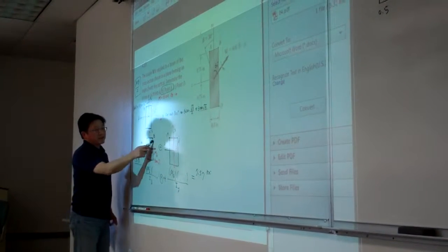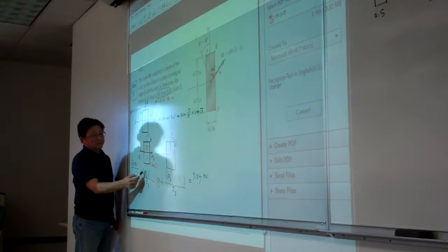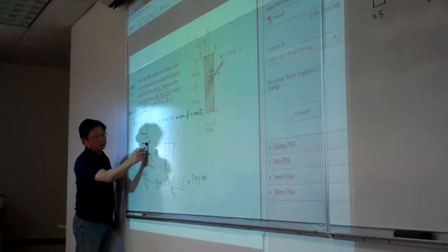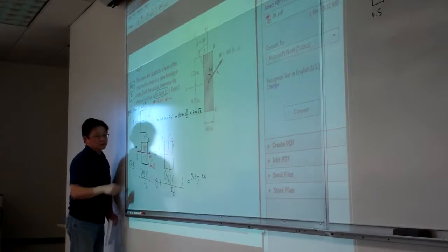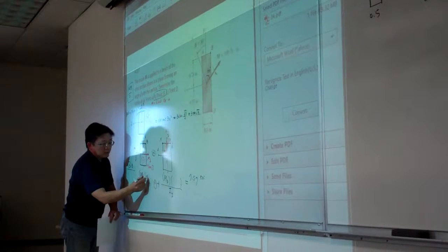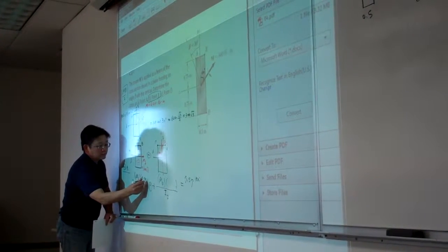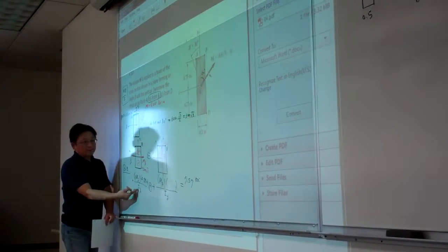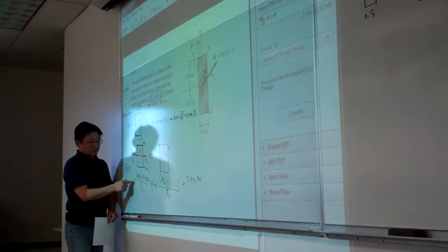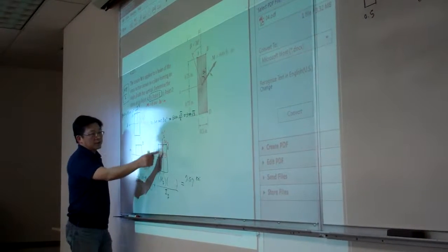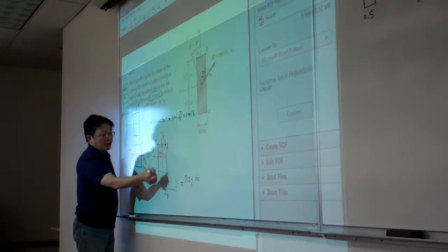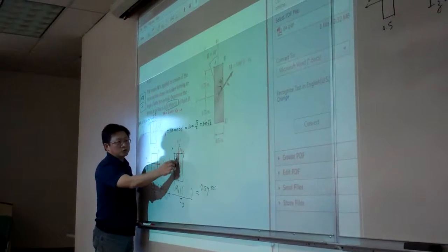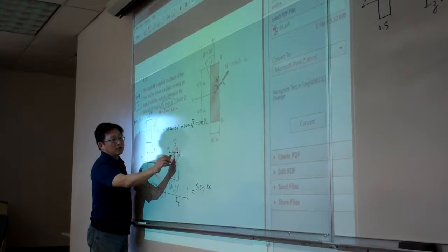Okay, now for this case, and again, the bending is MZ, B is here, and this is the distance from the point to the neutral axis, which is the same, 0.75 inch. And the same thing, I about the z-axis, the same thing here. And B is in tension, so positive. Now for this case, B is here. And this one represents the distance from the point to the neutral axis, which is y, so that is this amount, and that is 0.25.